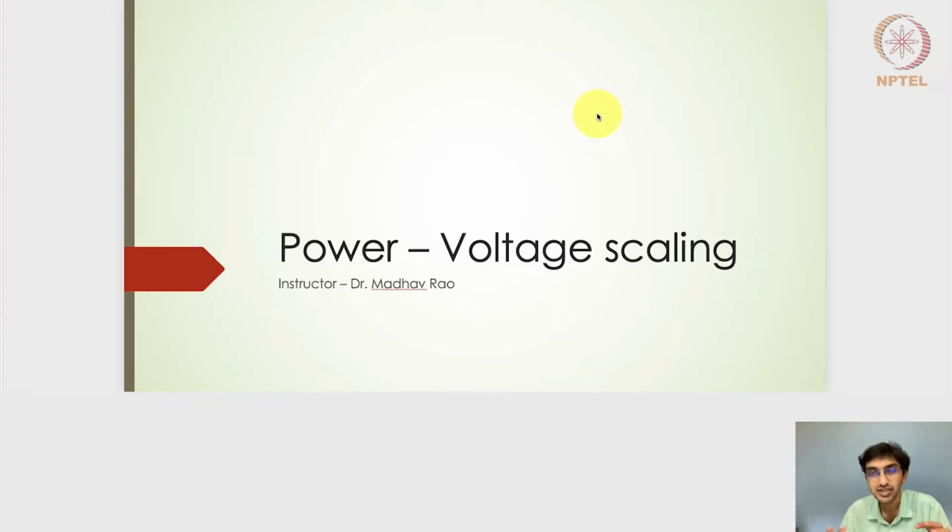So in that sense, the SoC design, the chip design, is divided into several components. One part of the chip area or the chip layout will be designed with the lower rail voltage. The other portion or the other footprint of the chip design will be designed using another rail. So it could be a lower rail design on one part of the layout, and an entirely different rail on the other side of the chip.